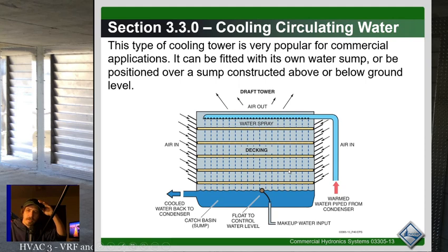And it's a very efficient way of exchanging heat on a condenser. The cooler the temperature, the more efficient the system's going to run, and you can get this water to a lower temperature than the actual air temperature because of the latent heat of evaporation, or latent heat of vaporization, if you want to say it that way. And that allows you to basically exchange more heat through latent heat removal. The point is that you can get it theoretically as low as the wet bulb temperature.